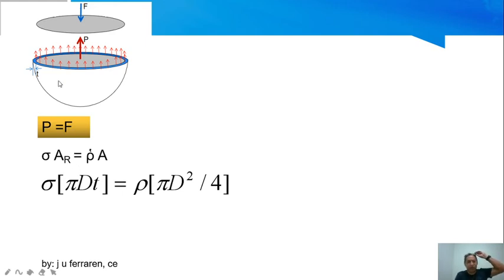Being a thin-walled container or vessel, the circumference, being a circle, has a formula of pi d. Then simply multiply your circumference with the thickness. So this is the resisting area. Then for pressure, this is not part of the notation. The correct notation for pressure is simply this one. The area is the area of your circular section, the area at which the fluid pressure is acting. So pi d squared over 4.